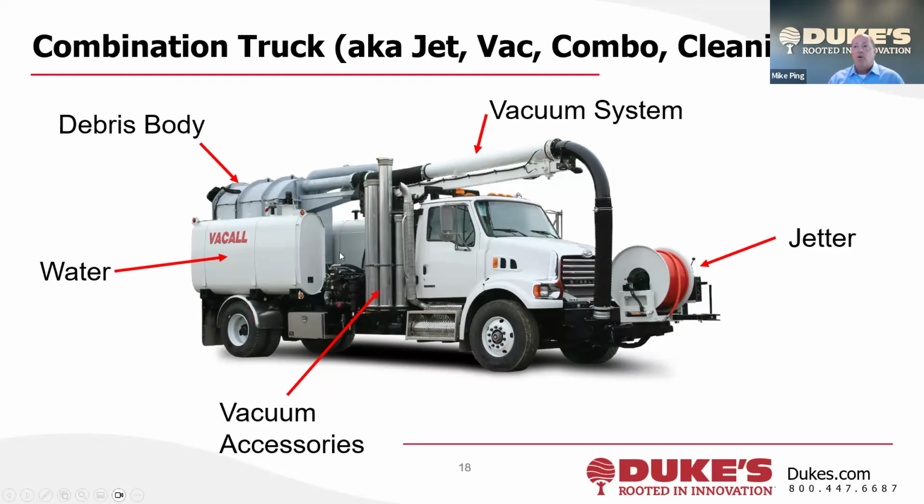So there's typically one on each side, right? And it's for the jetting system that's over here on the right. This jetting system is very similar to a pressure washer, like from Lowe's, right? A pressure washer from Lowe's, the little two-wheeled one, typically jets at maybe 2 gallons per minute. It would be very normal for this truck to jet at 80 gallons per minute, right?